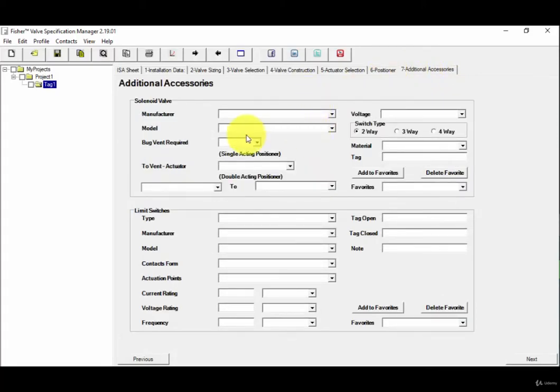That is a solenoid valve. As I told you, sometimes the control valve will get a signal from the emergency shutdown system. So this solenoid is in the inlet to the diaphragm pneumatic signal. This solenoid valve will close and force the valve to go to the open, fail-safe position.